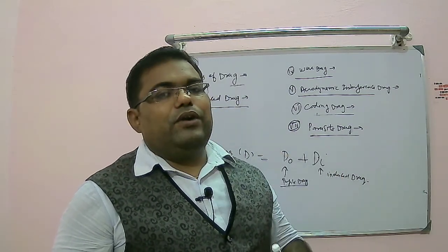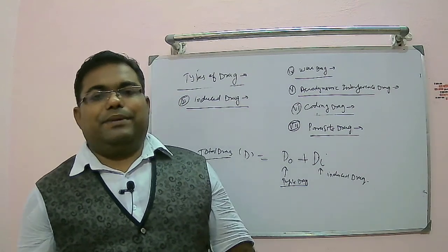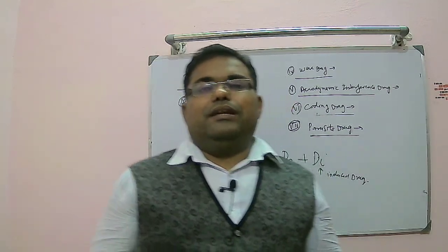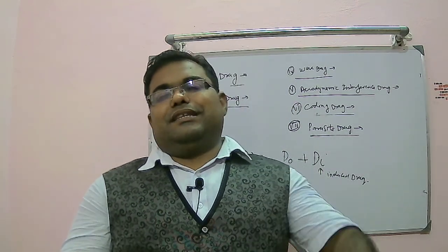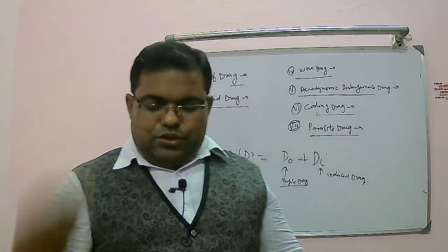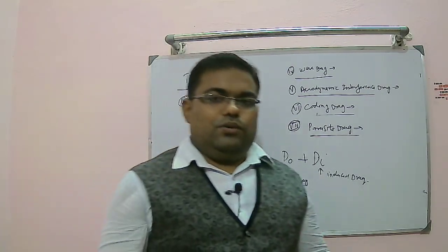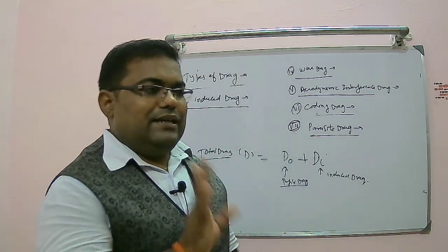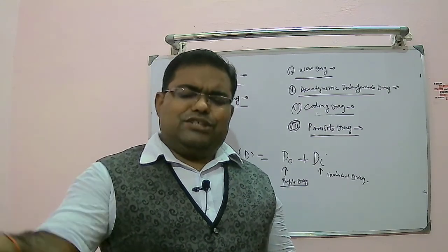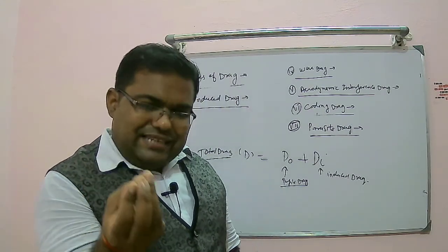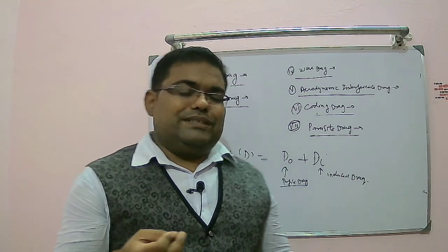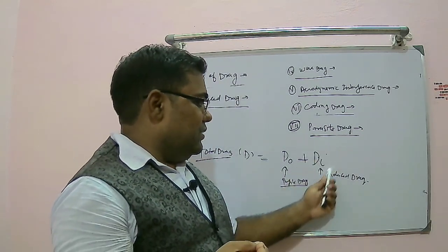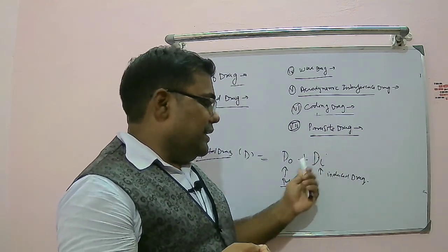How can we avoid them? By avoiding early separation on the top surface, by energizing the flow by any means, right? Use any method to energize the flow and make it turbulent so that it leaves the trailing edge very smoothly. At the end you will have a very small amount of vortices present. So 85% of the total drag is due to induced drag and 15% is due to profile drag.